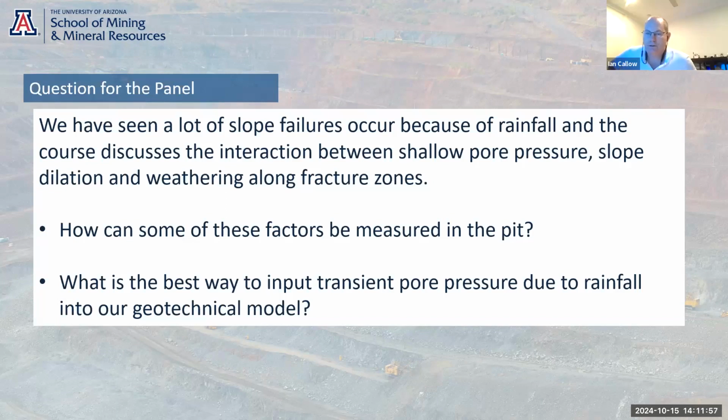Go ahead, Jeff. I was just going to quickly comment that, spot on as far as I'm concerned from a Rio Tinto perspective, and I guess from everyone else as well. There is a temptation from sites that if a piezo is dry, to stop measuring it. As hydros, we understand the processes. The geotechs have a different view of the world. They tend not to operate in a transient world. And so, for your site, you really need to maintain the monitoring right through.